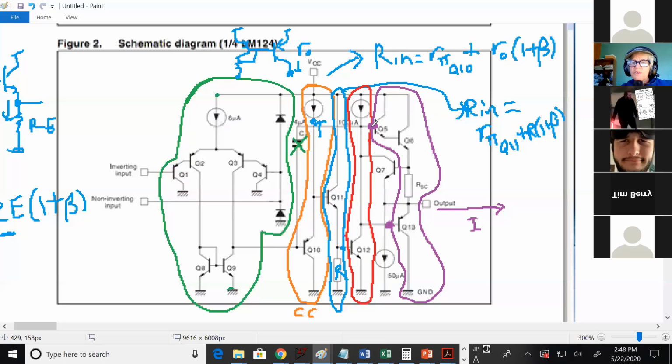So what's the voltage difference between the base of Q5 and the base of Q13? Oh, it's 0. They're tied together, right? Yes. And therein the problem lies. Yes, exactly. So this one, again, like I said, some of these schematics are cleaned up, but this one is definitely, as drawn, going to have crossover distortion.